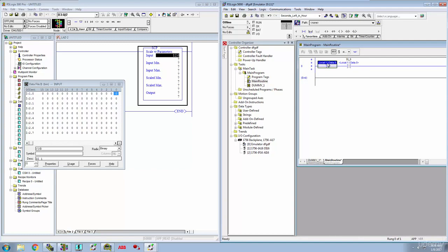I used the direct memory location for this one. I actually addressed it to the address. This one, I addressed it to the tag, and it referenced the address all the same. So we can still use tags, we just have to set up aliases inside of our controller tags or one of our program tags files, and we can address our I/O that way. So we still get to use tags, but yes, we are going to be looking at the addresses, and that's a handy thing because that tells us exactly where that thing is every time we reference it throughout the program.